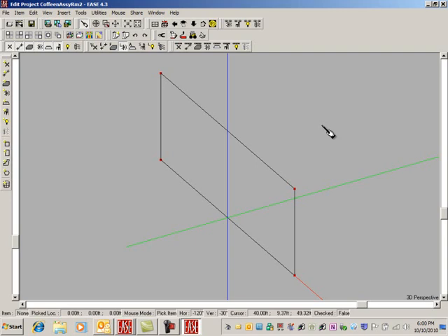So we could simply take this point right here and duplicate it in the minus y direction, 79.23 feet. A right mouse click says, what do you want to do? Duplicate. We don't want the z to go anywhere to begin with. We're going to do the floor. It's 0, flat floor. But the y is going to be minus 79.23 feet. Pretty close. Say, okay. Okay. And now we can, again, look at that. There it is.